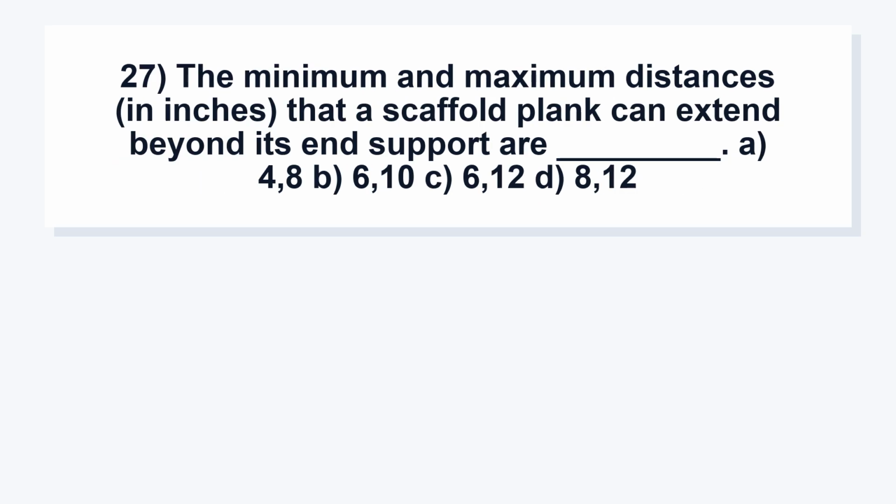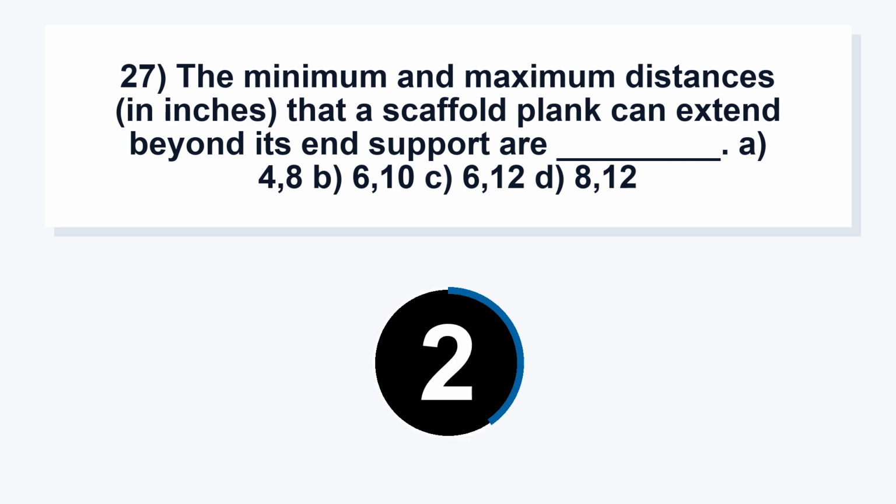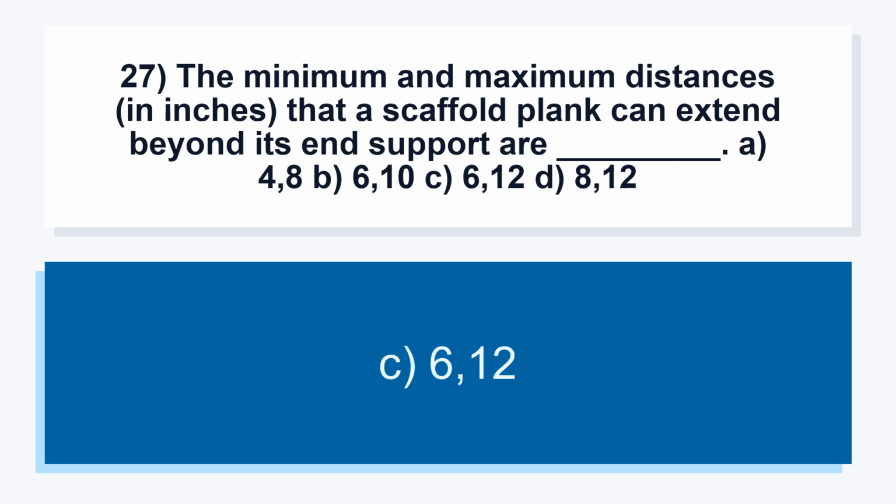27. The minimum and maximum distances, in inches, that a scaffold plank can extend beyond its end support are: A. 4 and 8, B. 6 and 10, C. 6 and 12, D. 8 and 12. C, 6 and 12.